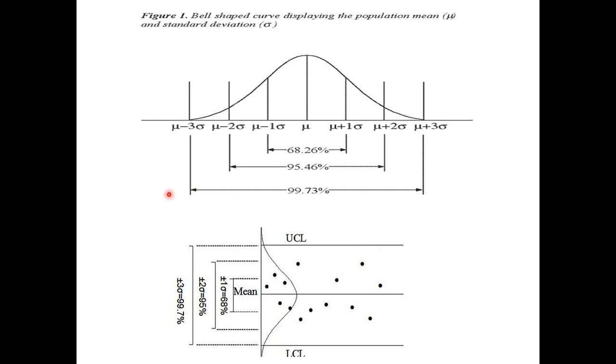By right, the upper and lower control limits are actually based on the third statement of your empirical rule, which states that 99.7% of total observations will lie within plus minus 3 standard deviations of the population mean. I do hope you get this correct.